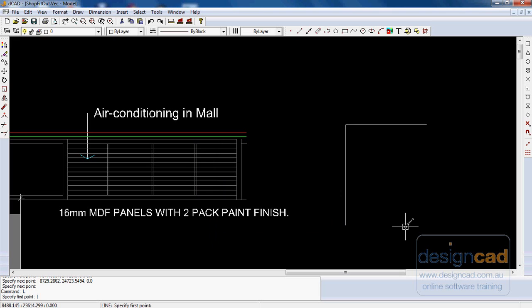If we start the line command again with the L shortcut and move, you can see here now I'm going polar at 45, and I can also reach 22.5. So I get divisions of that 22.5 degree step. So you can see those, being aware of those settings and the values that are burnt in there is very important. You might also notice that as I move my mouse, it being the distance indicated in the polar settings,